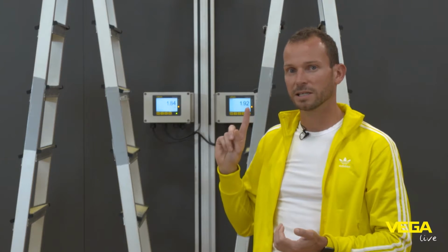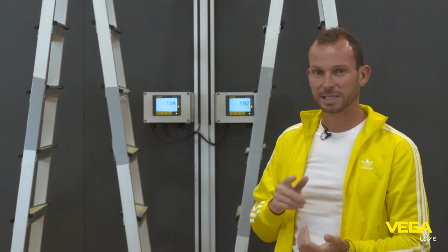What is important, if they're installed on the top of the silo and looking inside, there are some challenges. A lot of time there are installations inside of the silo. There could be also segmented containers or vessels. And a lot of time we have very narrow silos which are very high. In all these cases, we need a good focusing of the signal. And what is the difference between ultrasonic and radar if it comes to focusing, we will see in this live demonstration.